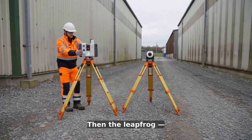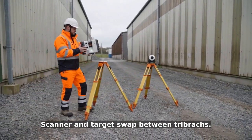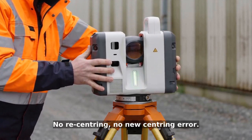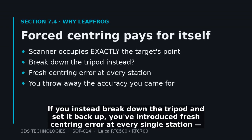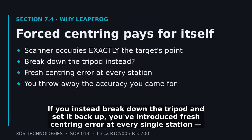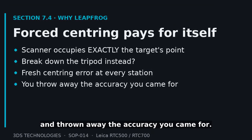Then the leapfrog, the mechanical heart of the Traverse. Scanner and target swap between tribrachs. The tribrachs never move, no recentering, no new centering error. If you instead break down the tripod and set it back up, you've introduced fresh centering error at every single station and thrown away the accuracy you came for.